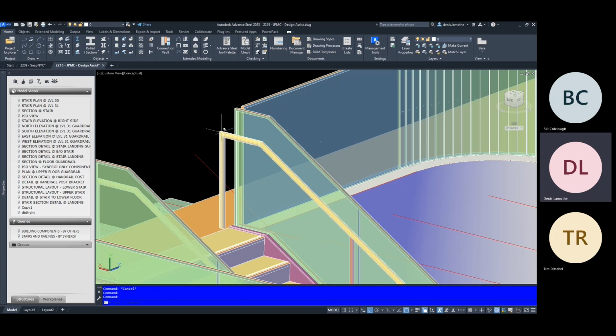It's possible the architect may have had some kind of exception to their permit where they're allowed to do less. Great, you know, that's on them. But we will always strive to make sure that we do 12 inches. And again, like I said, if it conflicts with the architect's design, bring it up to the PM's attention, or maybe make a note in the drawings that it is extended to 12 inches to meet code requirement.